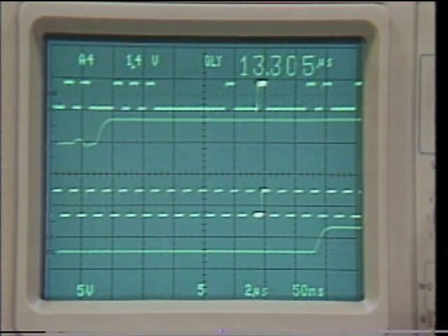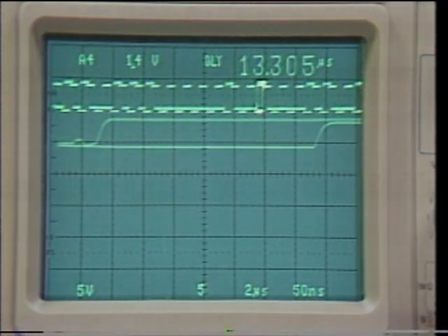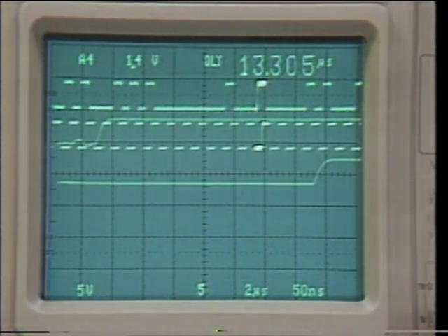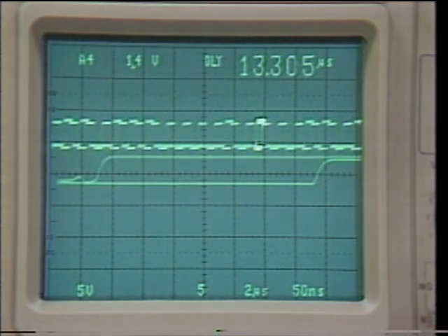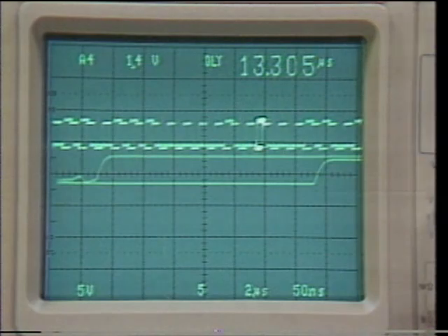If we superimpose these signals vertically, we should do that on the center graticule line, and count the divisions, multiply by 50 nanoseconds, we will have a slightly more accurate measurement. However, the convenience of the delta time measurement probably means that is the preferred method.